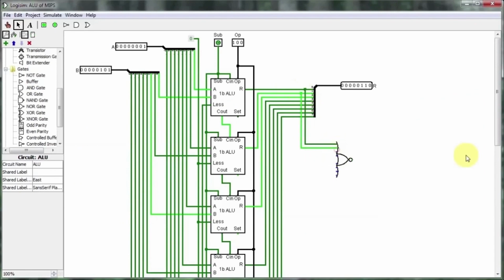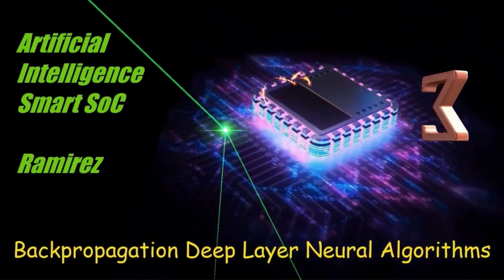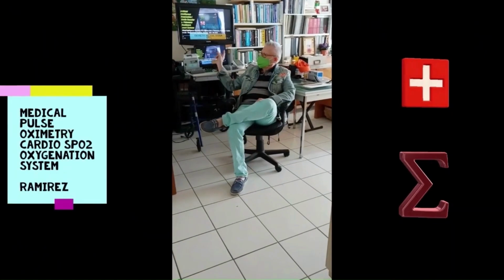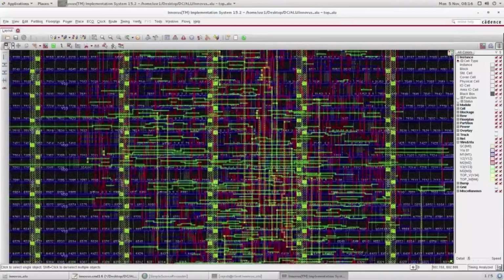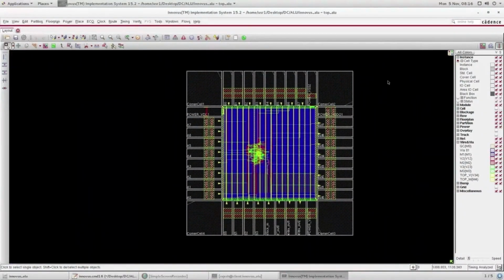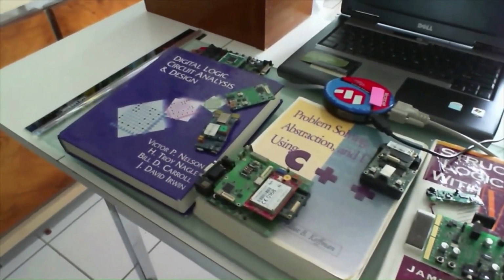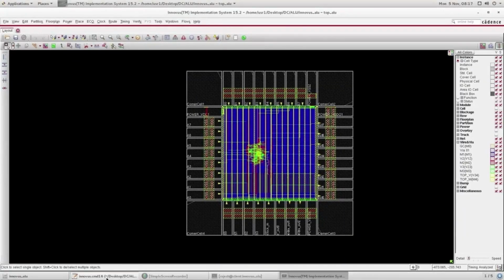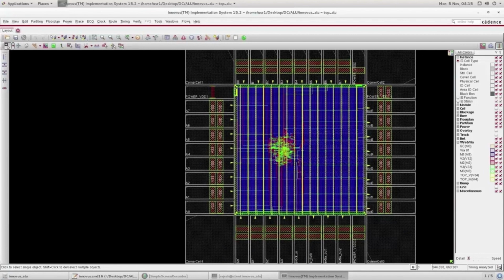The routing program receives guidance from the clock optimization program for nets in clock and other timing critical trees in the form of floorplan routes. The routing program breaks each of these multi-pin nets into a group of point-to-point subnets. Each of these subnets is then routed to match the delay selected by the clock optimization program as closely as possible to achieve the desired electrical and noise characteristics. You can specify the wire width and spacing to be used for each net. Clock nets are often given a wider width and spacing to reduce their resistance, capacitance, and noise.